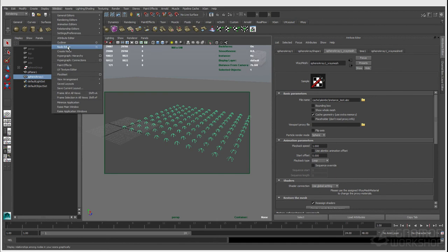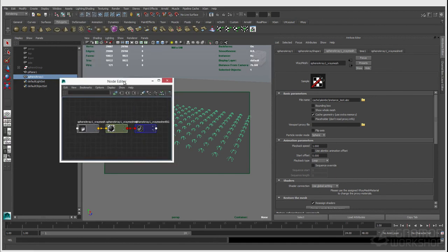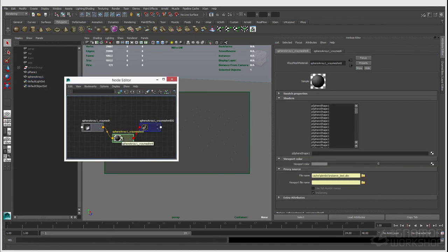So Vray does go in and automatically create my Vray mesh material. In this case, though, the Vray mesh material is a little bit different because we have a Vray shader slot for every single object in my scene. Also, because they're all sharing the same shape node, this is probably not the best example that I am just grabbing. I wouldn't totally easily be able to tell what was what in this situation.